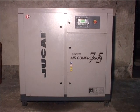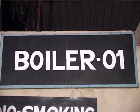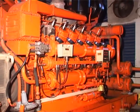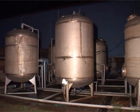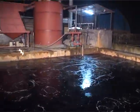After the finished fabric godown, we are in the compressor room. In the compressor room we have compressors for running the airjet machines and also other dyeing and finishing machines. We have two boilers for our captive generation of steam required for various processes, using compressed natural gas. For continuous supply of power, we have captive generation of electricity using a diesel and a gas generator. We have a 50 meter cube per hour water treatment plant for a continuous supply of soft water to various wet processing zones. We have a 50 meter cube per hour ETP plant for continuous discharge of effluent water.